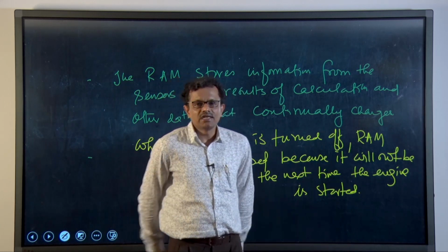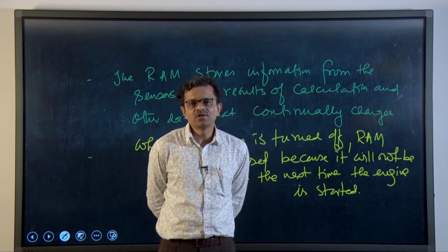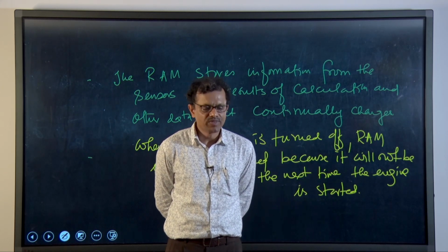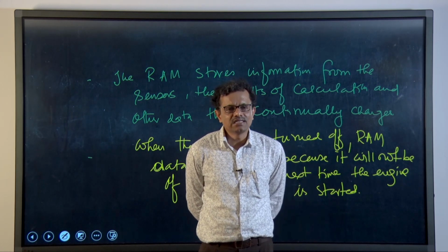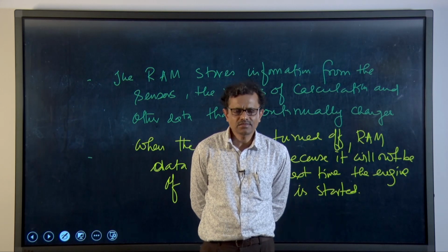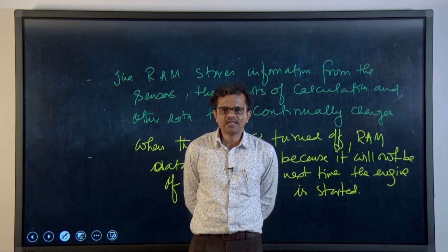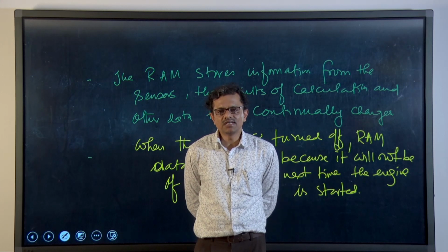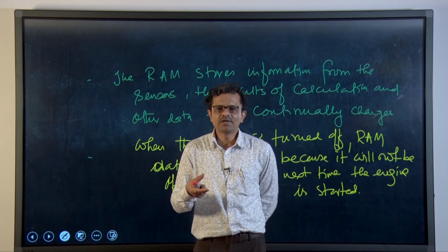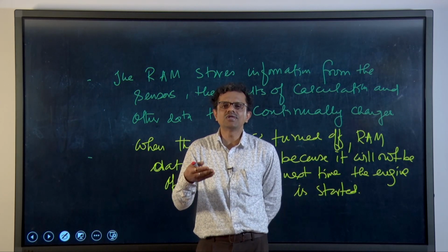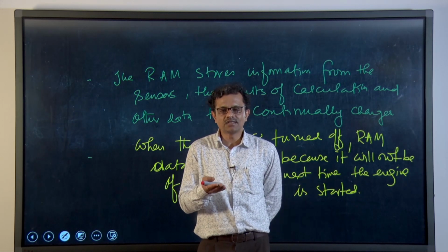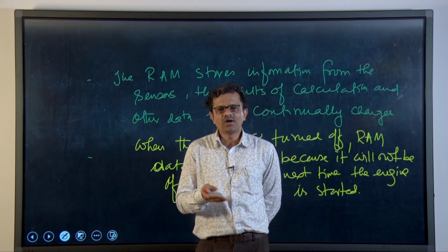So, this is all about two different types of memory chips, which are very important for the microprocessor functioning, and the microprocessor is an important element of the ECU. Now, let me tell you one thing. We have studied sensors, and we have seen that typically the input to a sensor is a physical variable and the output from the sensor is an electrical signal, and that electrical signal will go to the microprocessor, and the microprocessor will give some decision to the ECU on what to do next. So, the signal that comes out from the sensor or sensors is either analog or digital.